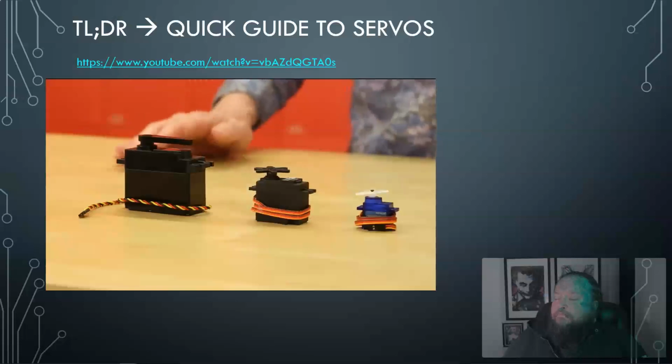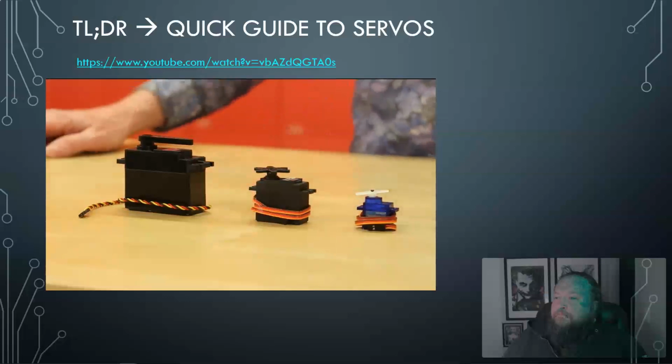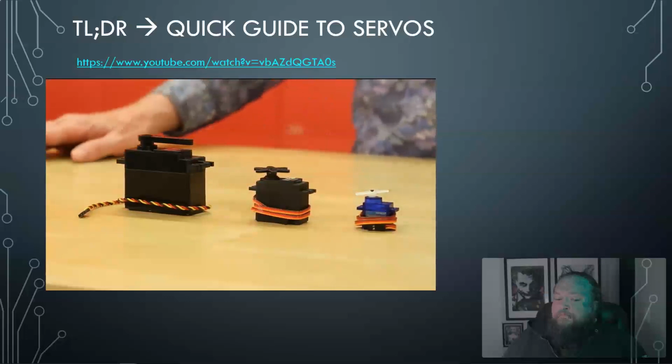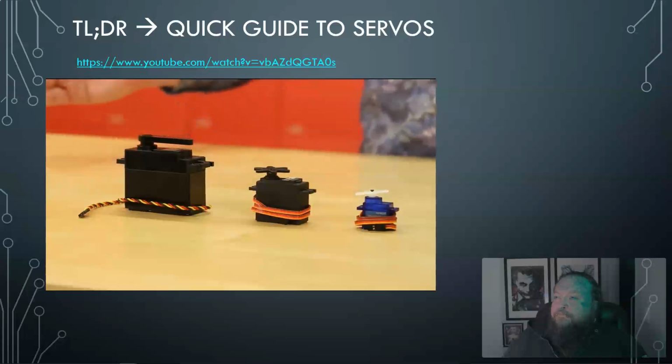Servo motors generally come in three sizes. There's micro, there's standard, and there's jumbo or giant. All are controlled the same way with three wires. There's power, usually 5 volts for a hobby servo, ground, and control. And control is done via PWM, or pulse width modulation. The servo expects to see a pulse every 20 milliseconds, and the width of that pulse determines the position.